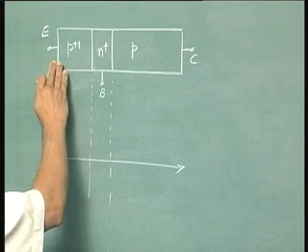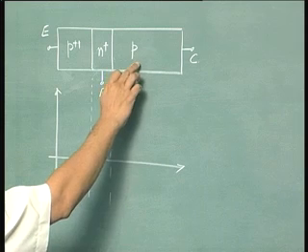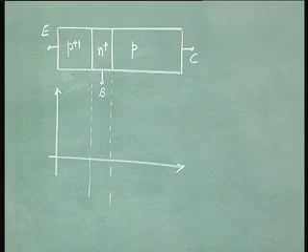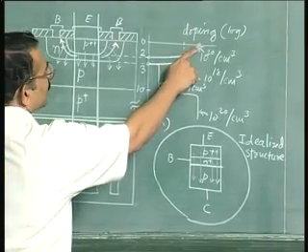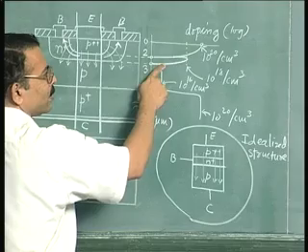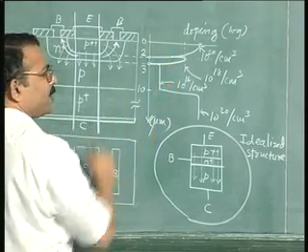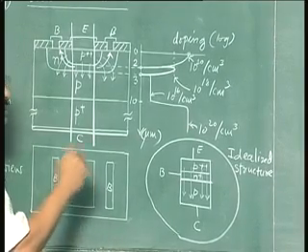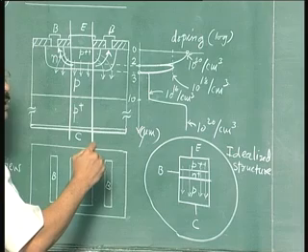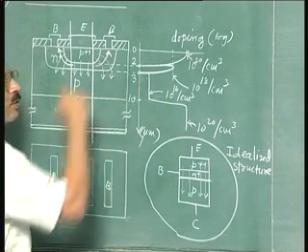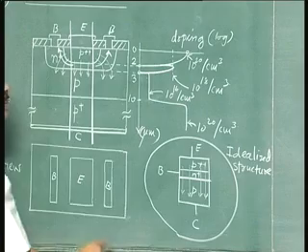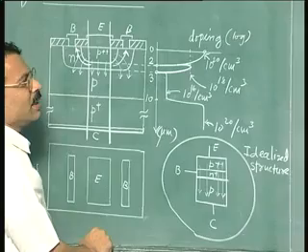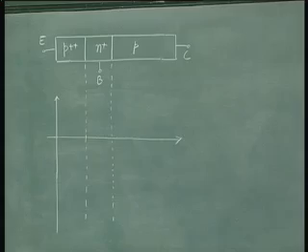Now, apart from the simplification that we have already considered for the device structure, one more thing that we will note is that though actually the doping profile is highly non-uniform, and this non-uniformity of the doping profile does have an effect on the bipolar transistor action, however, the basics of the transistor action is not due to the non-uniformity of the doping profile. So therefore, in our first analysis, we will assume the doping to be uniform in each of these three regions, meaning that the junctions are assumed to be abrupt.